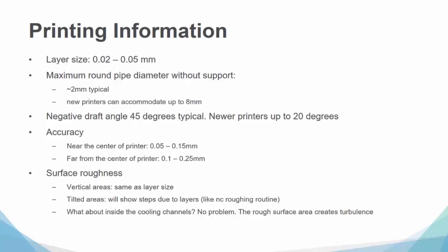It's pretty much the center is the most accurate location for printing. So typically with a core cavity, we'll put it dead center on the tray. That's where we'll print it. And as it goes further and further away from the center, we lose a little bit of accuracy. Plus the surface roughness, that's something of concern to everyone. As we build up layer by layer, that does incur a pattern in roughness. Basically, you think of lasering the powder. It goes through a shrinkage.